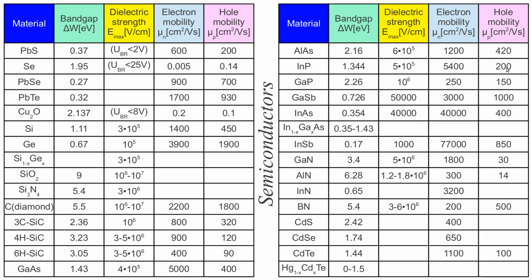Please don't take these numbers. I took these numbers from several sources, and on the same material, usually many different sources disagree on the values of electron mobility and hole mobility, depending on the way these parameters were measured. So I tried to compile this table out of average values I could find in the literature, but the literature on many occasions disagrees by at least a few percent on the measured values of electron mobility and hole mobility. The same about the electric strength, they also disagree. The only thing we can measure accurately is the band gap of the semiconductor.